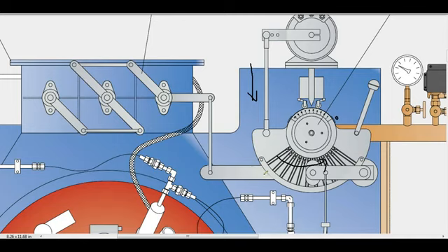And what happens to the air? Since the cam is moving up and down depending on the boiler automation system, the cam is attached to this through the linkage here, and then this link is controlling the dampers.